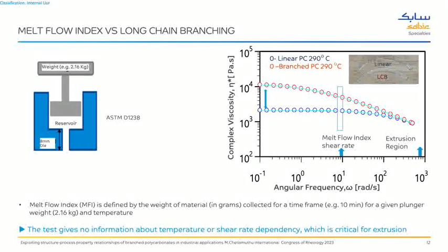So the way it is made rheologically is that you unravel the entanglements at a particular shear rate and try to catch the viscosity at high shear rate, but at the same time it has a low viscosity. It helps in some processes as well. So this is pretty unique, and long chain branching can be very tricky sometimes. It's pretty difficult to say, even though the melt flow is low, it may or may not process, but actually it flows very well in high shear processes. So that is something I want to point out in terms of long chain branching.